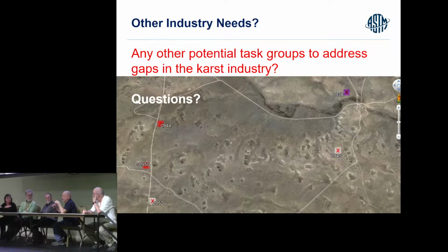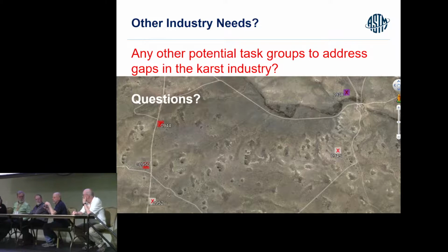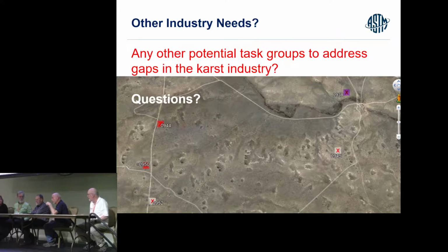But you have to use a different curve for your stormwater calculations in karst than you would for a standard area. And as you increase the amount of impervious, the difference gets even more. So stormwater management in karst has its nuances, and it is considerably different than it would be for non-karst areas. And the current standard is written for just generalized non-karst areas.